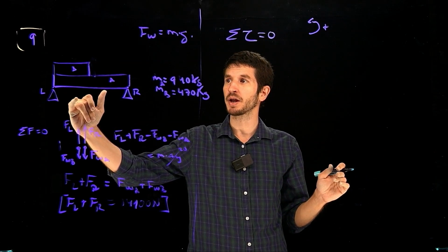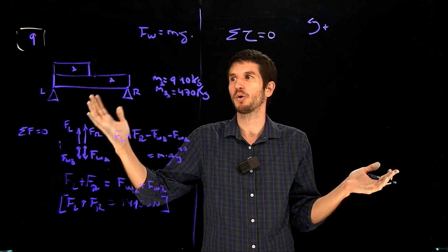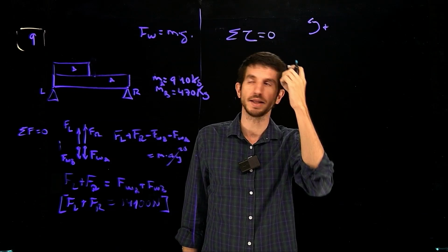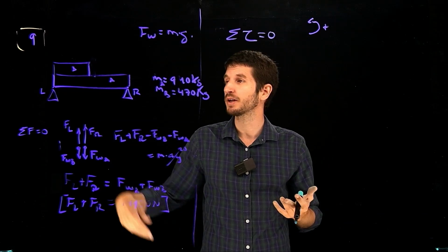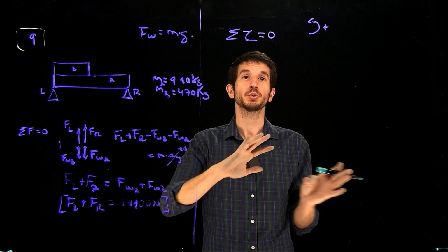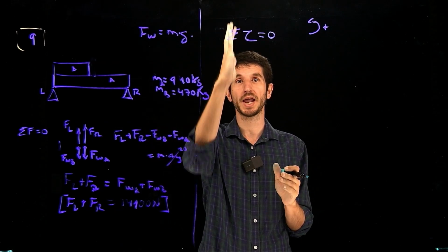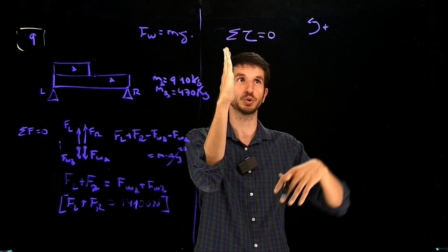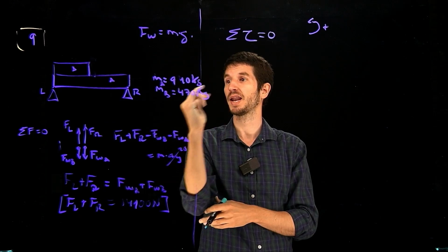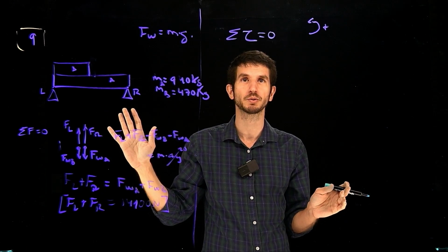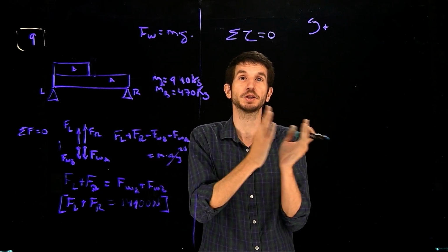And the second thing we have to choose is the origin, about which we're going to calculate all the torques. In this particular case, we can choose whatever. It makes sense to use one of the fulcrums, so we get rid of one of the unknowns. Why? Once you align the axis upon which you are analyzing rotation with one of the forces, that force goes out of the equation, because that's that force times the distance, but the distance is 0 because it's at the axis itself.